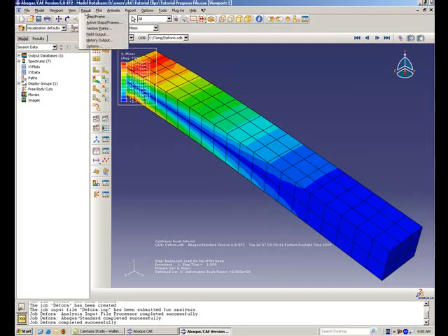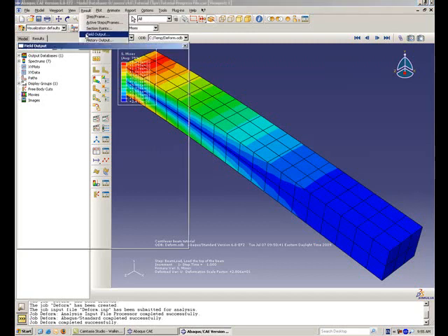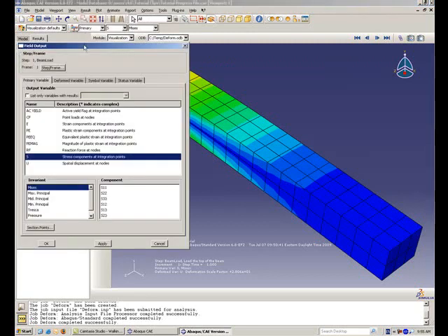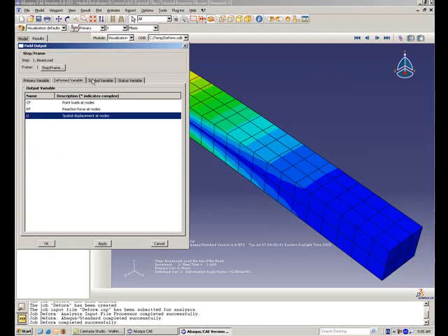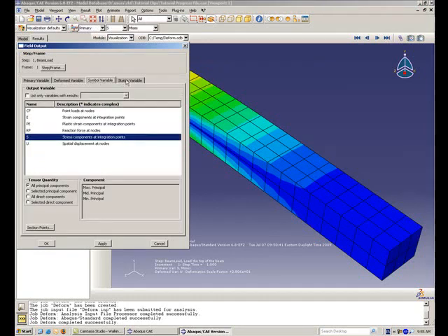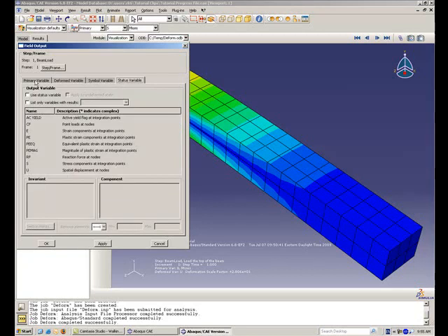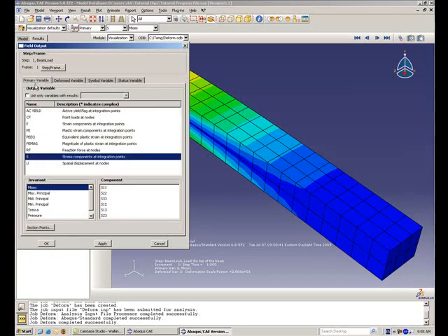You can change the variables displayed by the contour plot by going to Results in the main menu bar and then clicking on Field Output. Try examining this feature. There are numerous ways to view your results in the visualization module, but we will only discuss how to view the deformed post-analysis model and how to show the stresses on that model.